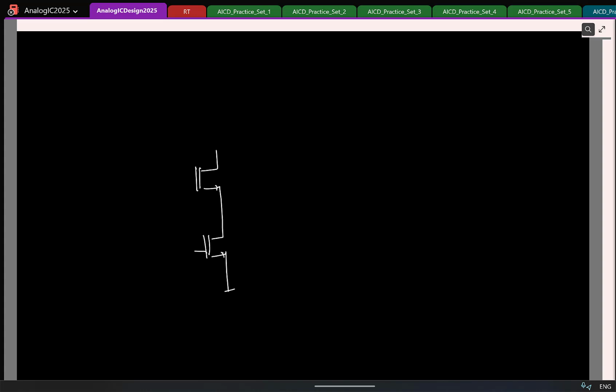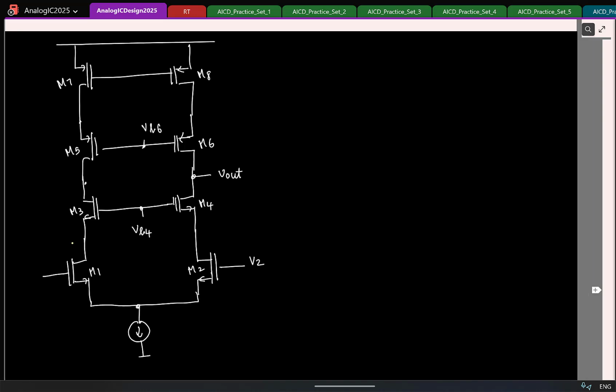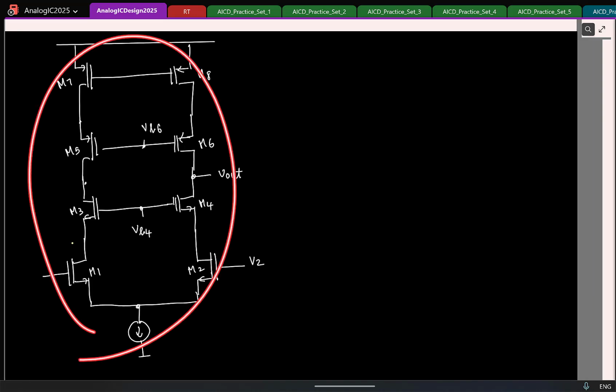So this is your normal cascode. So what is the output resistance here? If I call this M1, M2, Gm of which transistor? Gm2 R02 times R01. Roughly this is the thing, and using this we basically made a cascode like this.